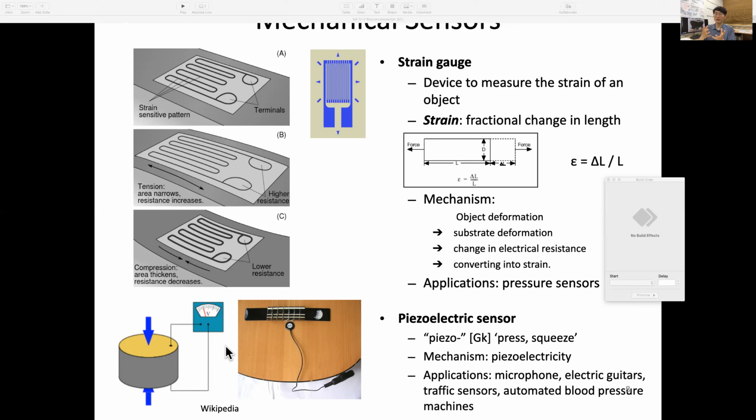In fact, this piezo can be used in reverse, which means you apply a voltage to the piezo and the piezo will deform. In my PhD thesis, I used a linear piezo. I gave a certain voltage to make the piezo displace in the tens of nanometer range, a very precise and small displacement. People have used it for very fine displacement, in nanometer or micrometer ranges. For precise displacement, you can use piezoelectric sensors or actuators.